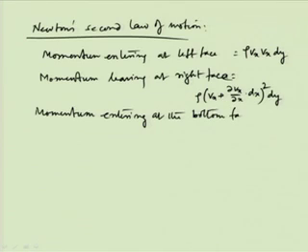At the bottom face, it is equal to rho Vy, which is the mass that is entered, and it is entered with a velocity and reaches this region with the x directional velocity. So, this is rho Vy into Vx into dx, and that becomes the x directional momentum.